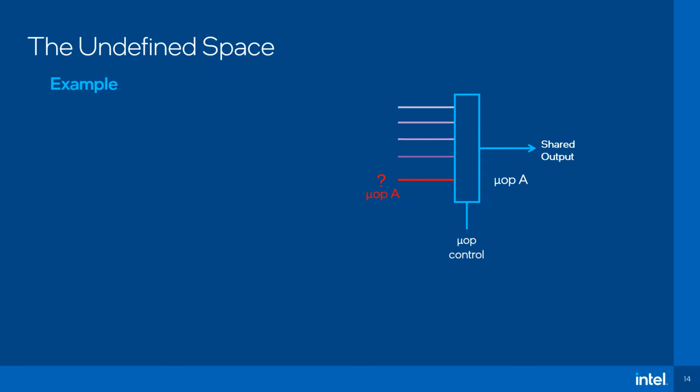For example, somewhere inside, there is a latch that was gated by another UOP B, the producer UOP, for power optimization reasons. The data on that latch can hang there if the latch is not open long enough. If UOP B held secret information and UOP A can read it, that is of course a security risk.